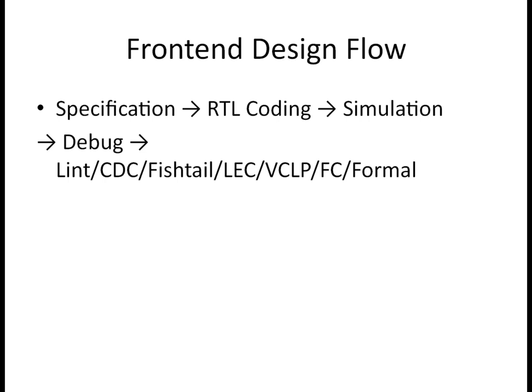For multi-bit, we have many synchronization techniques, and a few we are going to discuss today. First is the most common, the FIFO synchronizer. Then we have gray code encoding synchronizer, multi-bit synchronizer, and mux recirculation technique. Those synchronizers we use to synchronize multi-bit data from one domain to another.